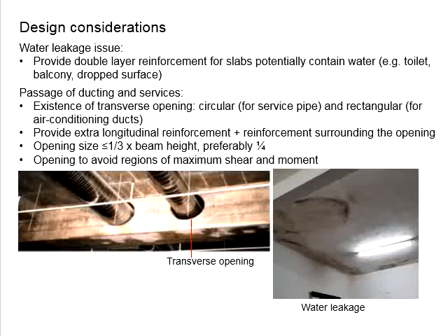You cannot fully rely on the contractor to provide coating at those parts, as some contractors may not provide it even though it is required by the architect. In the case of lacking supervision, or in the case that it has already been covered by the finishes and tiles, it is very difficult to cross-check whether there is damp-proof coating on those regions, and this is normally not noticeable by the client as well.